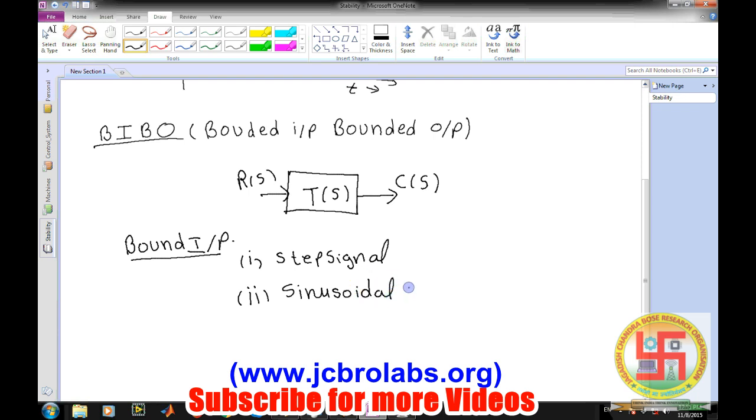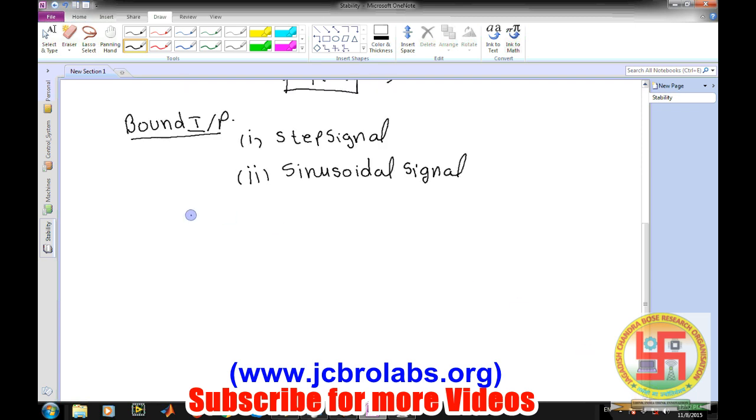A simple definition is that it is well within certain limits. It is not like the input is going towards infinity or outside the input parameters of the control system. For example, take a DC motor. If the input requirement is 5 volts, it should not be like you are applying 10 volts to the input. So bounded input means you are applying within the limits of that physical system, and based on that, stability means that if we apply this bounded input, the output should also be bounded.